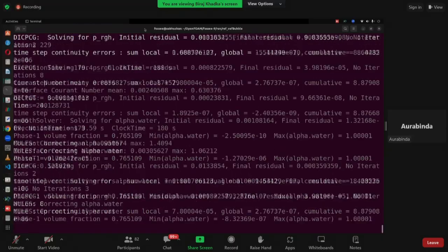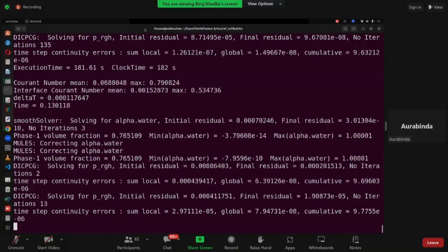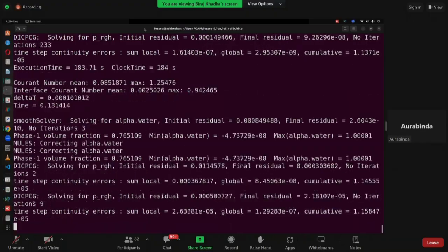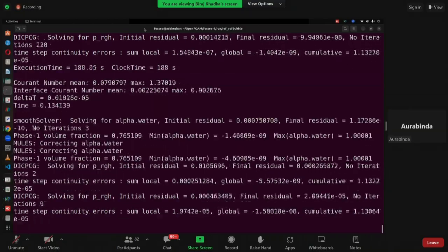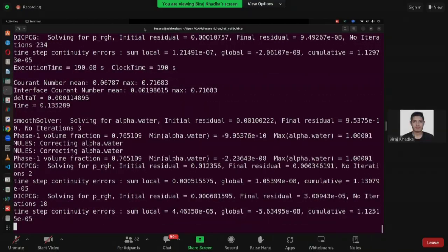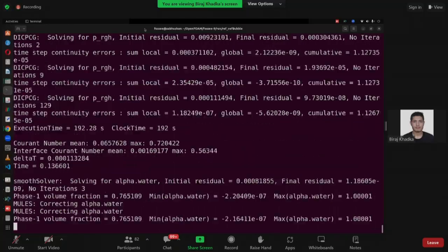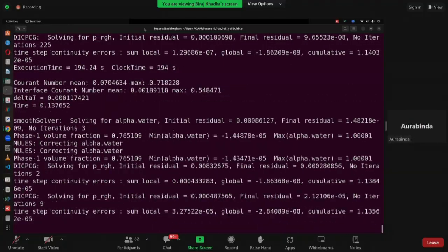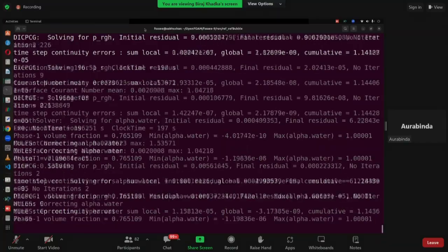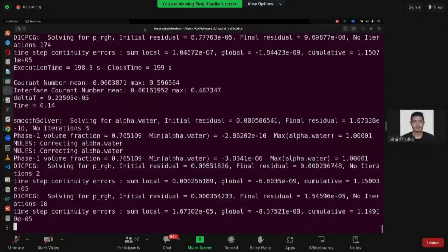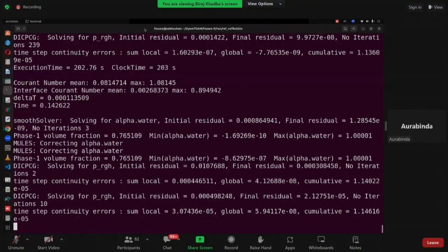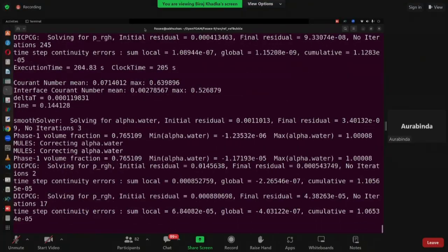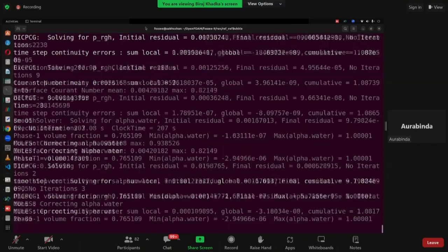In those boundary conditions, I have something to ask. Every time we are writing inlet, for example, type is inlet outlet, then inlet outlet uniform, we are writing uniform 0. If it is non-uniform, for example, a boundary where some portion is different and the other portion is something different, how can it be written?